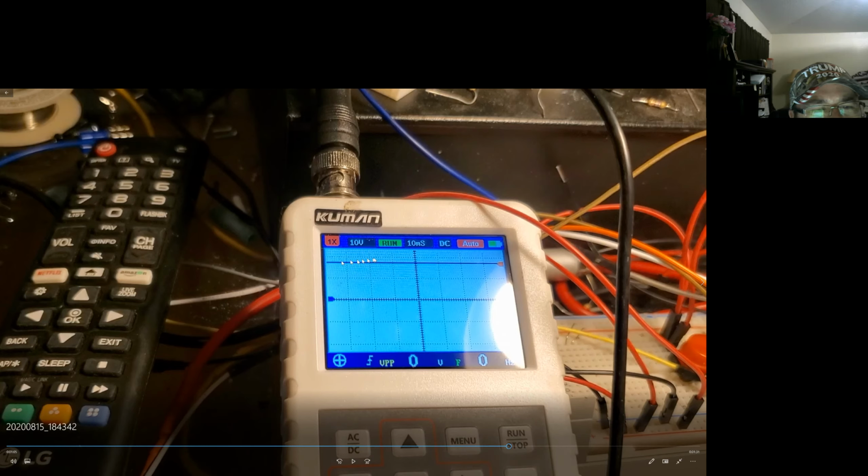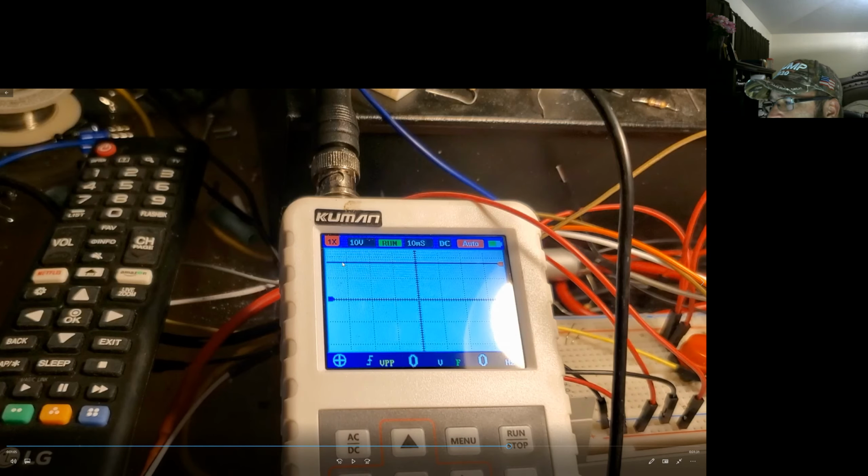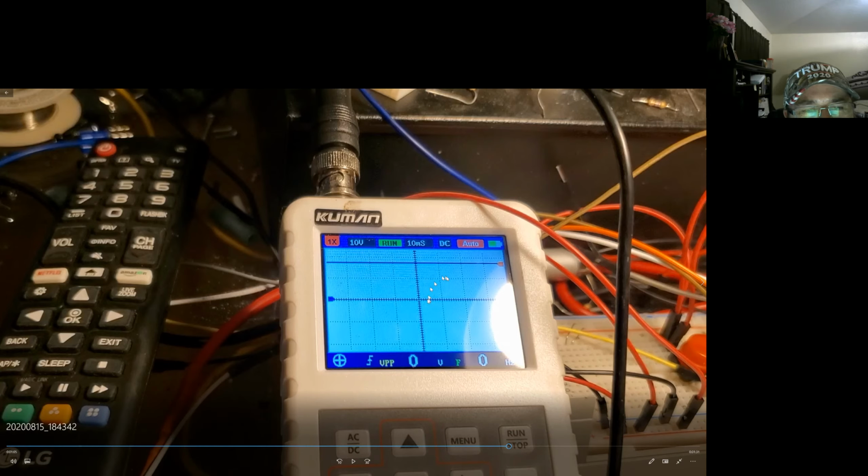You're gonna get just a flat level line. All that is, the capacitors get charged, and since you're not using current, you're not taking power out of the capacitors, they just stay charged up. And so you just see this flat line. You're not seeing the ups and downs because you don't see the downs, because a capacitor does not discharge back into the AC.